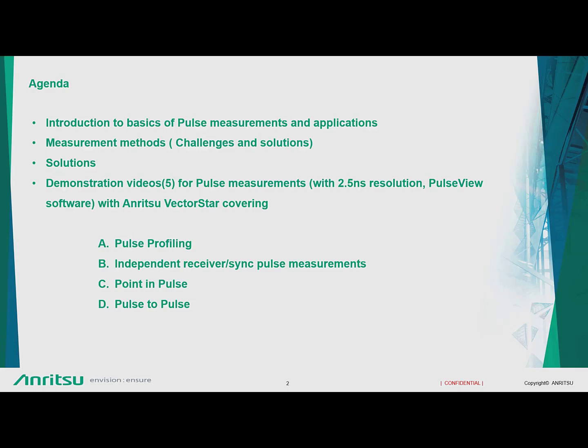There is a very specific application wherein independent receivers are required for measuring duties which either have long delay lines in them, or in fact if there is some filtering in a particular subsystem, then the transmit and the receive side, they have some delays on the measurement side, and that offset makes a lot of difference in the transmission measurement accuracies. So that's why it is very important to have independent receivers for VNA making pulse measurements.